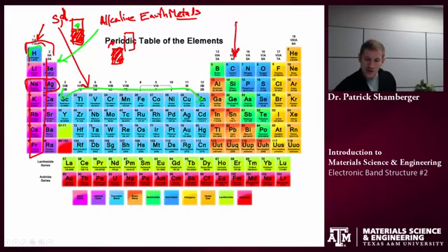Now, if I think about the traditional semiconductors, things like silicon, germanium, diamond is even considered a wide bandgap semiconductor, I have a picture that is roughly half full of electrons. So remember, let's think about silicon, for example. I have 4 valence electrons, and by the octet rule, I would like to have 8 for a full closed shell. So that's halfway full. And so what that means is that when I look at my band structure, I have exactly enough electrons to fill up that valence band, but I don't have enough to start filling up the conduction band.